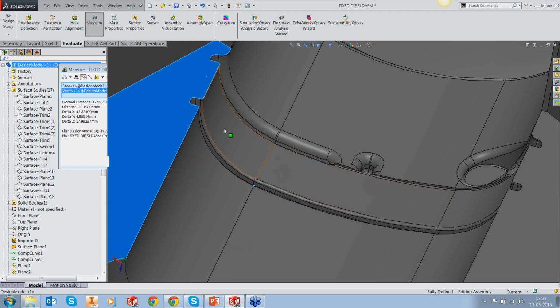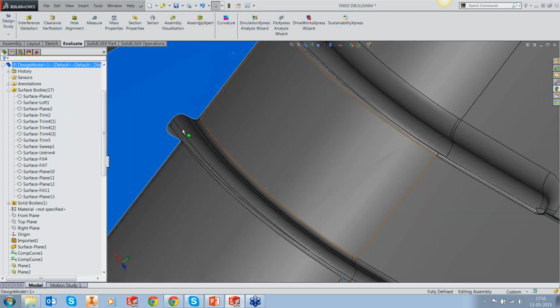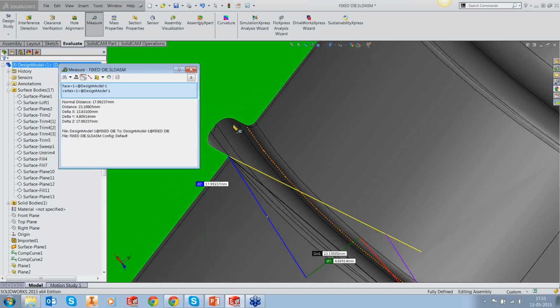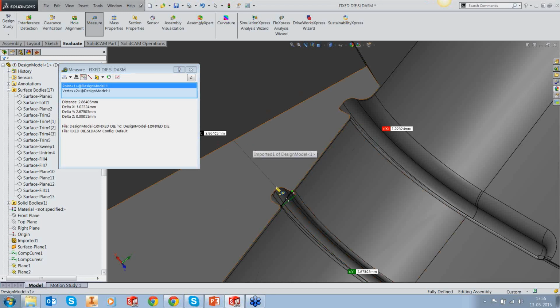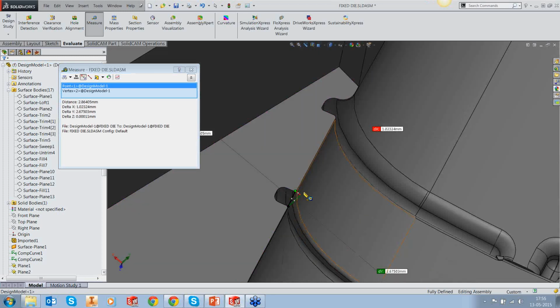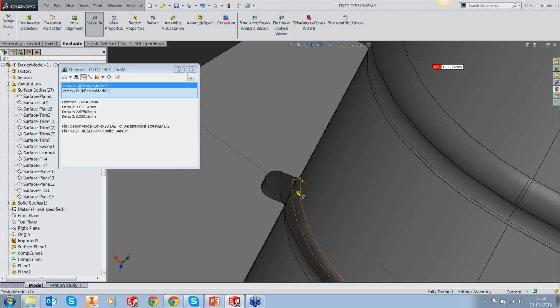And the size of the tool that would be needed would probably be roughly 3 millimeters. So imagine I'm taking 3 millimeters down to about 17 millimeters. That's an L by D of about 6. Generally, L by D of 6 is going to give you a disastrous result with such a small tool. So all you could probably do is take a 4 diameter tool and rough out as much as possible later in the local area, and then do an EDM on the remainder straight away.